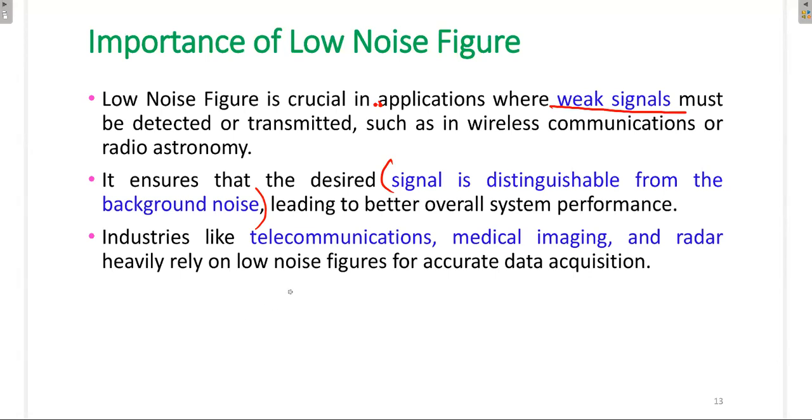Because already the signal will be coming along with the noise. If our system is adding more noise, then we cannot distinguish the signal from the noise, and we cannot get any useful information from the signal. It is used in industries like telecommunication, medical imaging, and radar. These industries heavily rely on low noise figure for accurate data acquisition.